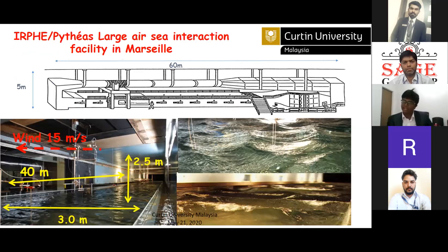So that was the wind tunnel, or we can say wind water tunnel, because that particular wind tunnel has been used not only for wind turbines but also for wave energy experimentation. In this particular setup, different wave heights, wave frequencies and wave strengths were also measured, as well as floating-type turbines, and without water we also test the turbine. So this is a multi-purpose wind tunnel with a dimension of 2.5 by 3 meters and 40 meters in length. It's quite big, so I used to go inside the tunnel and do the experimentation whenever it was required.